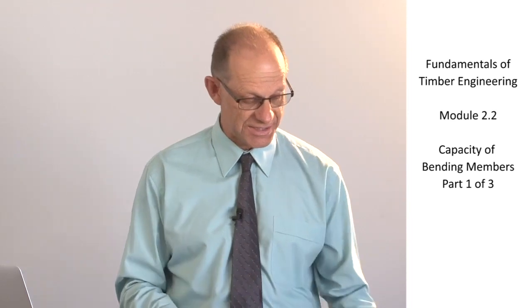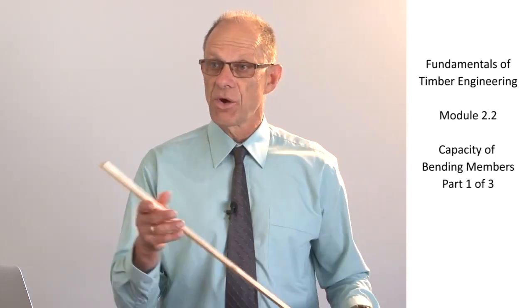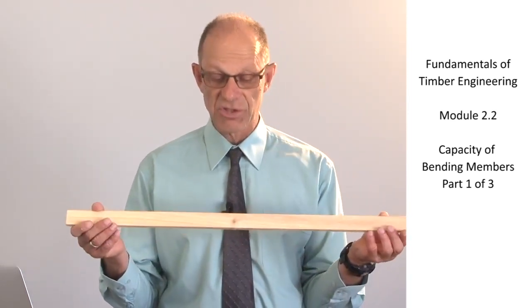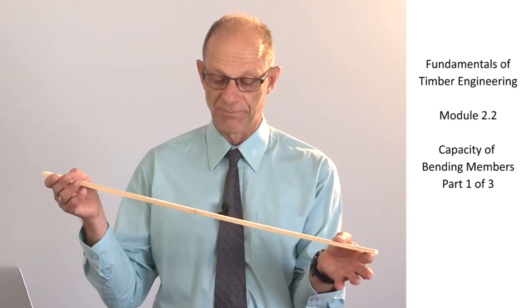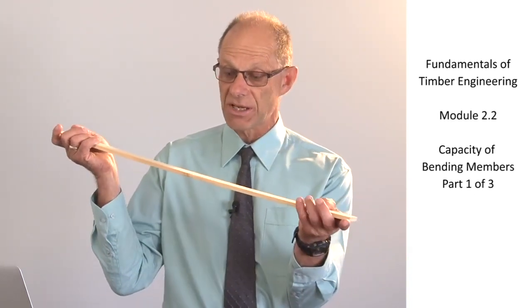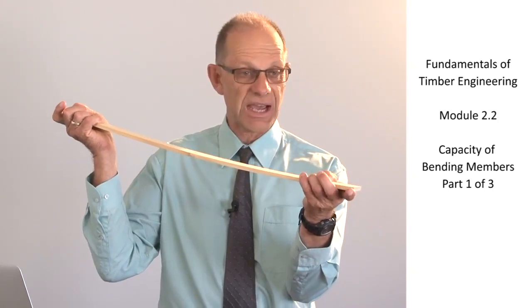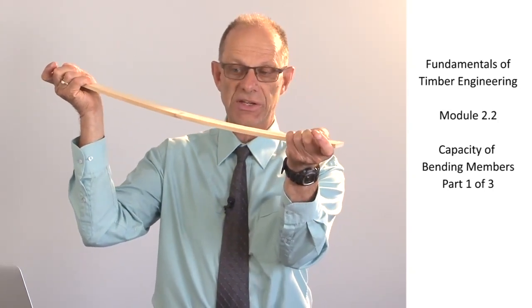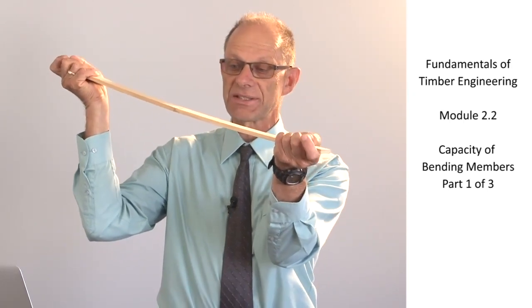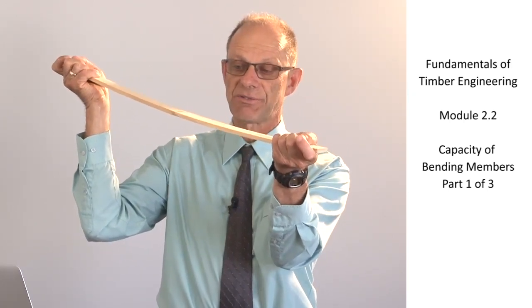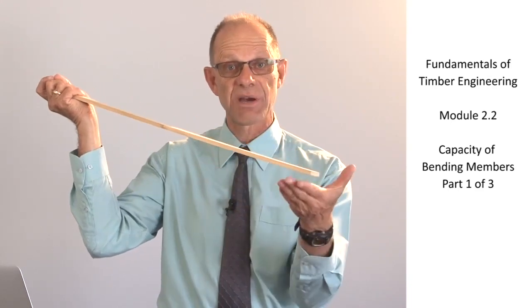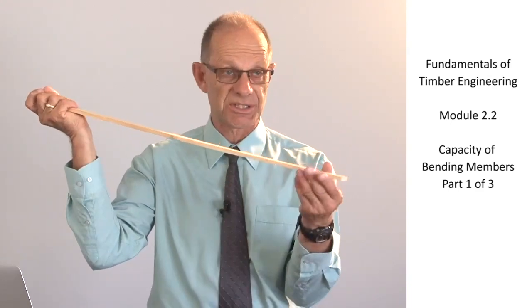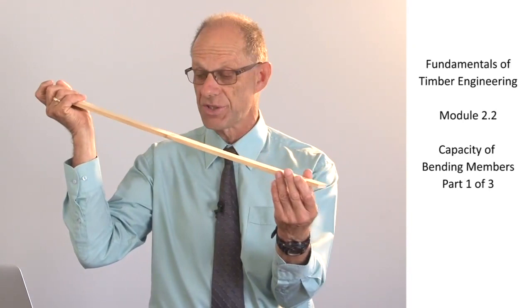Now, limit states. Essentially, when we're thinking about limit states, there are two that we often think about. The serviceability limit state we've already explored, and it is how does the member perform under regular loads? Does it deflect too much? So in this case here I'm applying small loads and it's deflecting a little bit. Is the deflection too much? The serviceability limit state is what addresses that question.